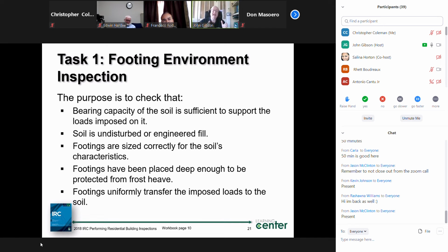And what we're looking at here is traditionally a spread concrete footing. So that means it spreads out to hold the weight coming down of the building, and it's going to be sized based on how much resistance you get from the soil interacting with that footing. If the soil won't bear the same per square foot weight of the building, then the footing needs to be spread out more until it reaches how much bearing capacity we have available on the soils.